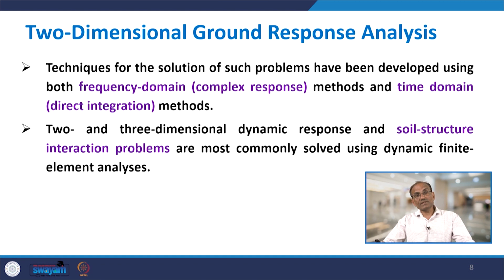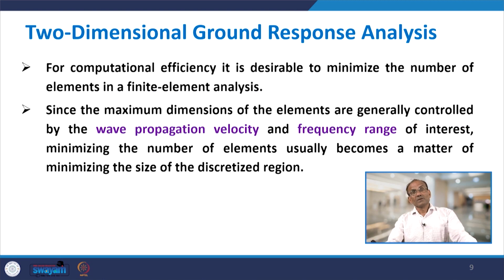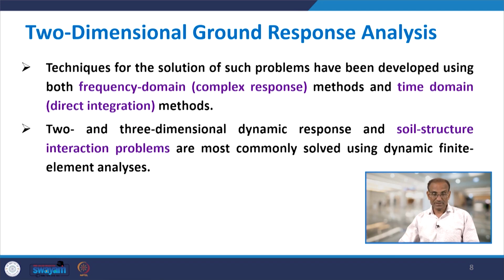Now, continuing with 2D ground response analysis. Techniques for the solution of such problems have been developed using both the frequency domain, which is the complex response method, and the time domain, which is the direct integration method. 2D and 3-dimensional dynamic response and soil interaction problems are most commonly solved using dynamic finite element analysis. For computational efficiency, it is desirable to minimize the number of elements in a finite element analysis. So, naturally, the 2D analysis we discussed will be carried out using finite element analysis.